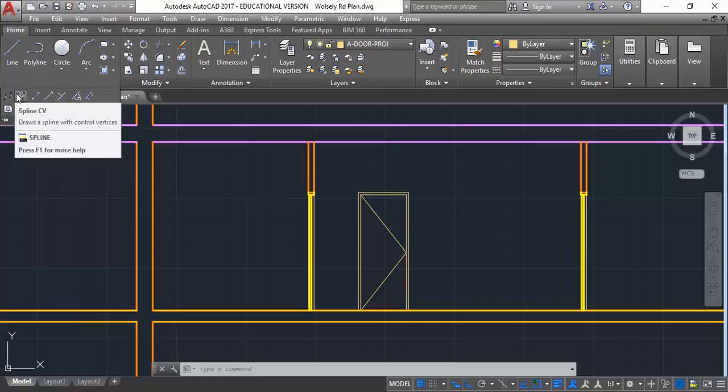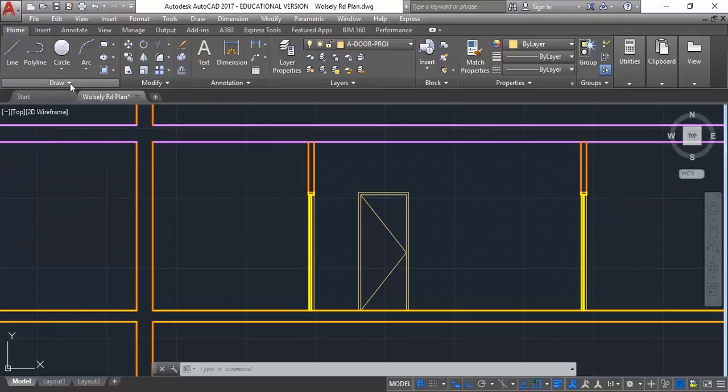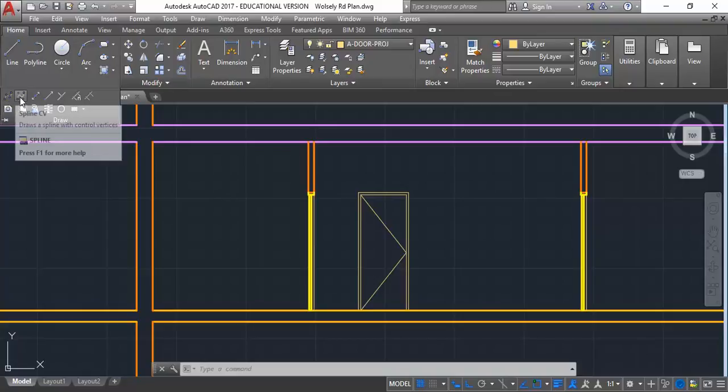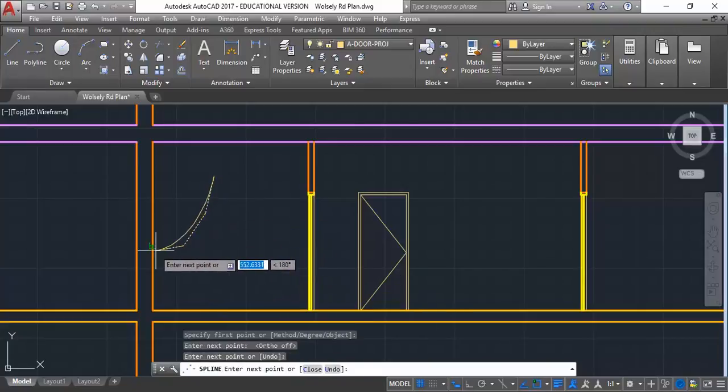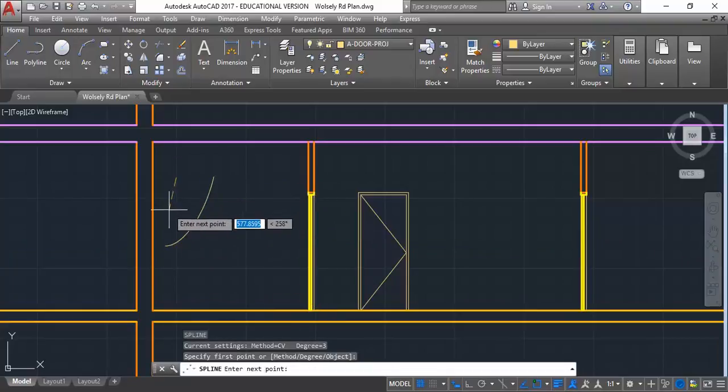Yeah. But like I said, if you want to try drawing it with AutoCAD, just to help you draw some of the lines, you do have these tools here under the Draw panel. You've got these different spline tools, and they're good for doing these sorts of shapes. I'll just do a few so you can see there. You can get shapes that you can't get normally. So that will give you something like a curtain.